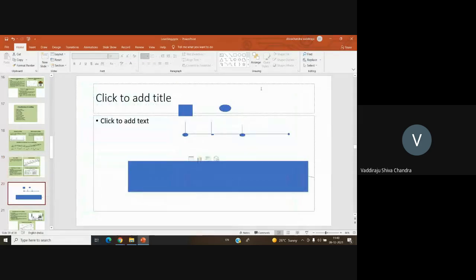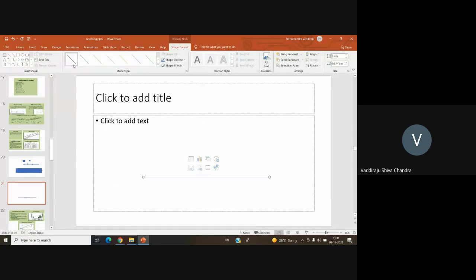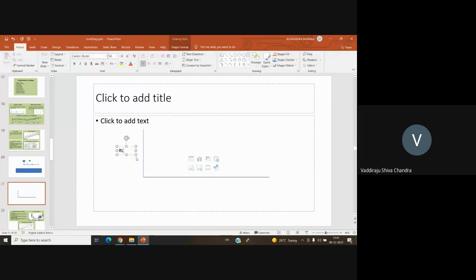After taking these readings, what we generally do is plot a graph, on the x-axis as well as on the y-axis. On the y-axis, we'll have the reduced levels. Here we'll mention the RLs, and here we'll mention the distances. So this will be 0 meters, 5 meters, 10 meters.